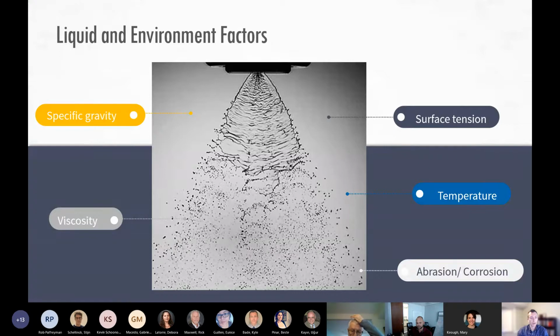And so in any gas processing or gas conditioning applications, having a smaller droplet is going to mean that the surface area of that droplet is greater and you have less volume contained inside the droplet that's not going to interact with the material. So as the viscosity is increased, that is going to resist the flow through the nozzle. And so you're going to end up with larger droplets because the material itself can't flow quickly and break up as it leaves the nozzle.